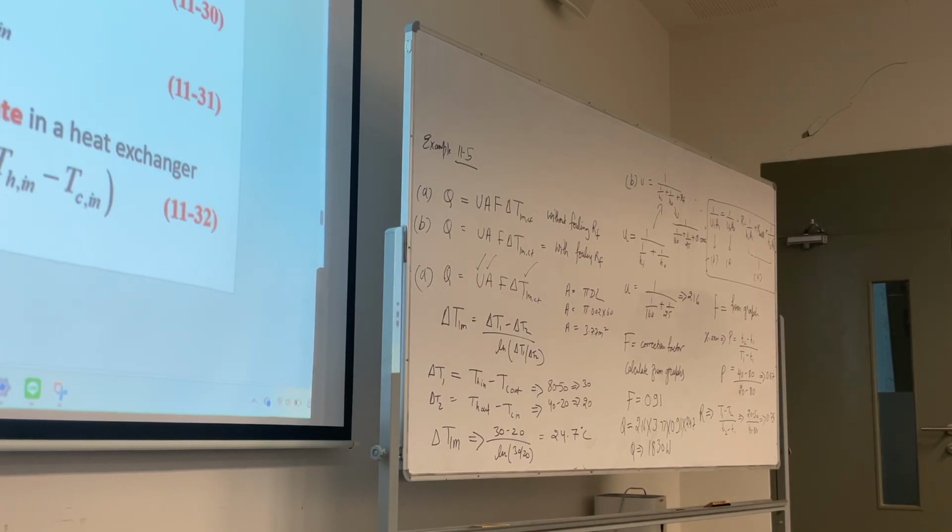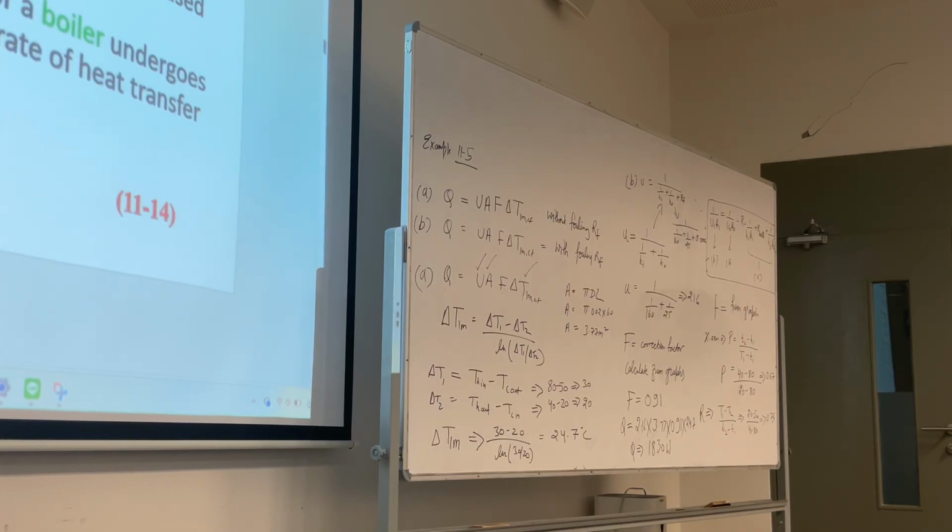Okay, epsilon is equal to actual heat transfer rate divided by the maximum possible heat transfer rate. It's a non-dimensionalized unit. Actual heat transfer rate in a heat exchanger, same like we have discussed in the previous example. Capital C is MC. M is mass flow rate, C is specific heat. So M and C they have written as capital C. This is your derivation. This MC is capital C, this capital C.